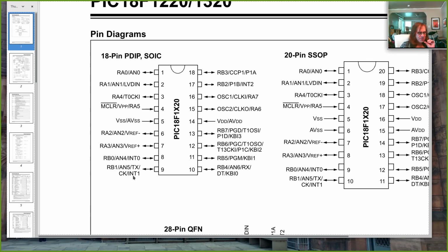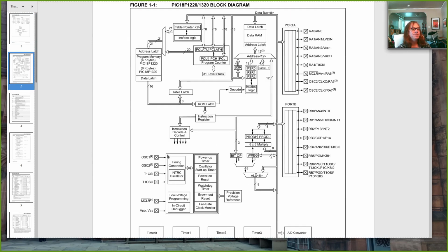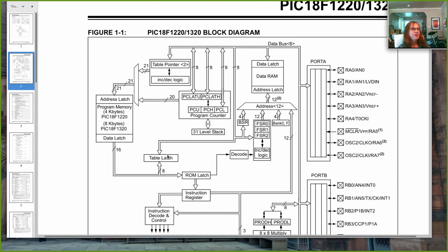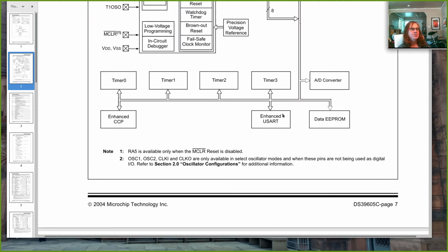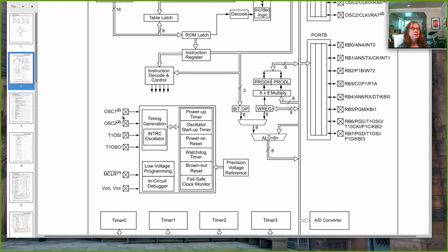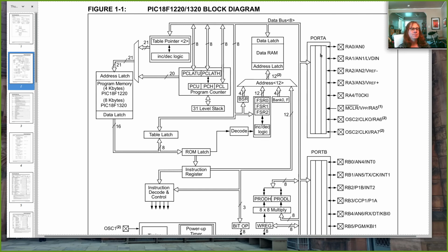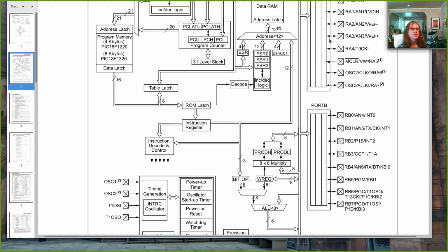And so what this means is that before we can actually use these pins to do something like read a switch or drive a motor, we have to tell the CPU which pins we want to use for what. Because, if you go to the data path diagram here, right? Here's some of the I/O systems. Here's some timers. Here's an analog to digital converter. Here's something for doing serial communication. Here's something for doing timing. Here's your ports that actually go to your pins, right?